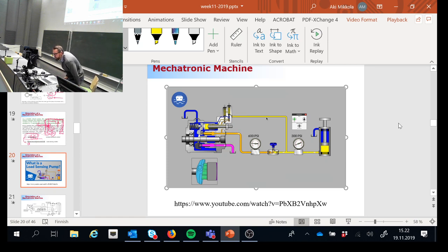And that flow compensator is receiving information, feedback if you will, coming directly from the load, our cylinder, which right now is working at 300 psi. That's the pressure it takes to lift the cylinder and rod. And that 300 psi is being fed back to the controller and giving that spring a boost. I can tell that the spring is actually set to 300 psi.